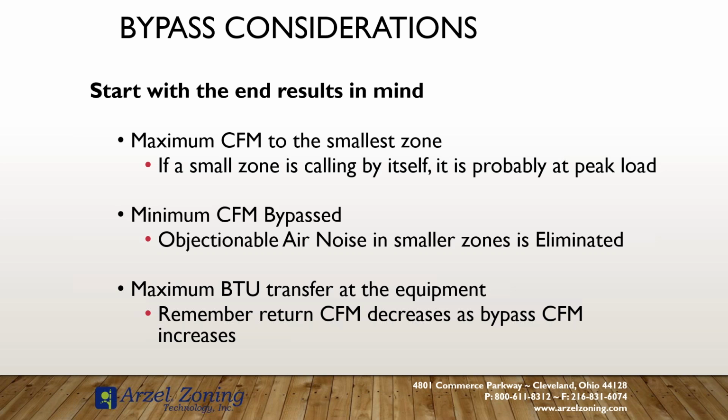So I need numbers to work with, and those numbers allow me to set it for what I've typically found to be the maximum tolerable pressure without creating objectionable airflow noise. And then I let my customer gauge it. If they say, yeah, it's a little bit loud, then I can make small adjustments, start cracking it back, and start dialing it in. And then I might take it to the middle range.